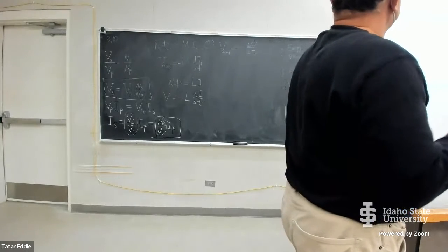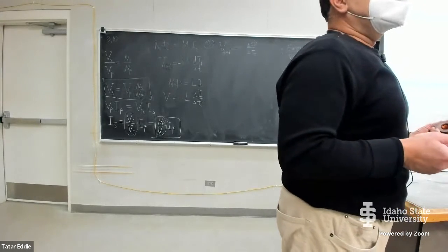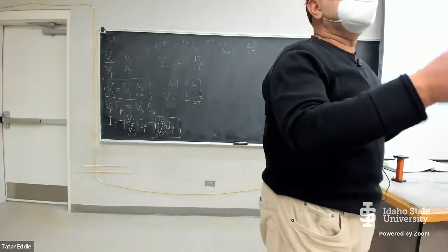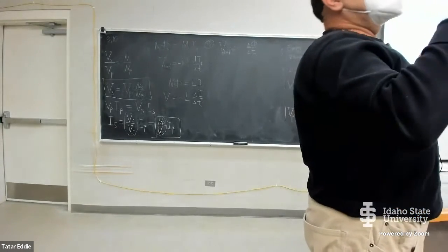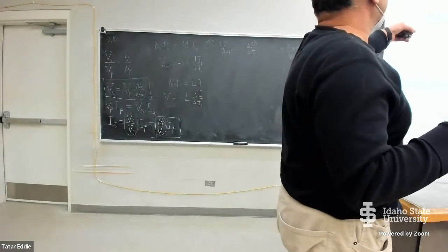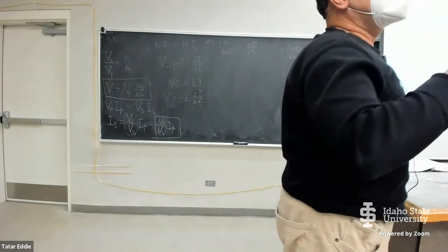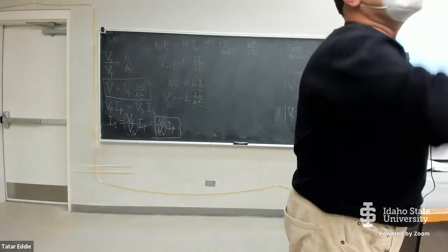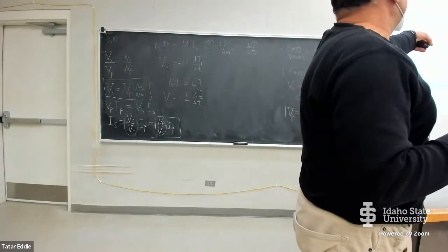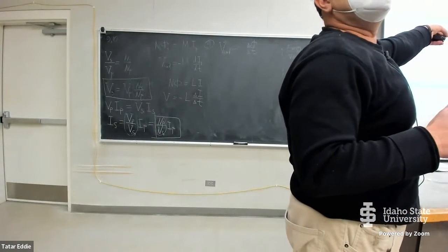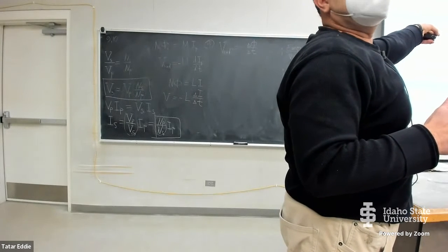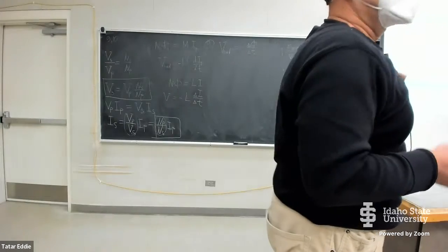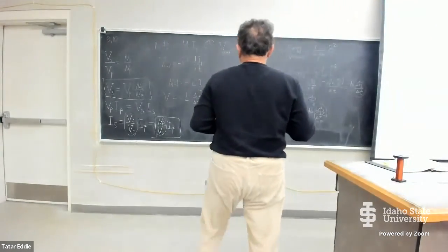And the question is, you have to put in some electronic circuit so that if the power stops and the magnetic field goes from 3 to 0, it goes slowly enough so that the induced voltage does not exceed the maximum amount of voltage that the patient can tolerate. Well, let's see.